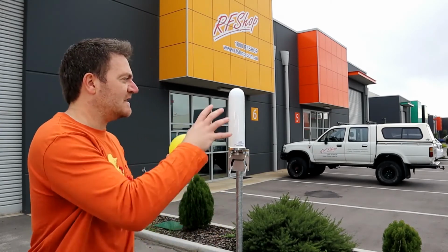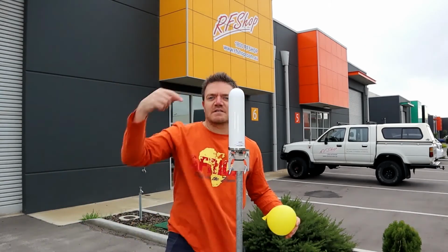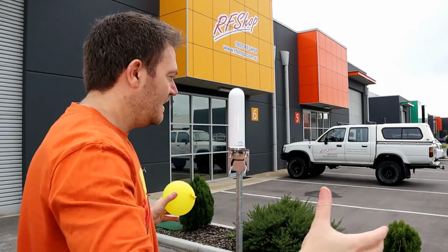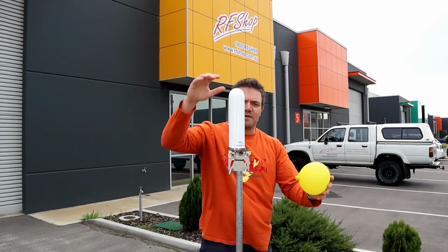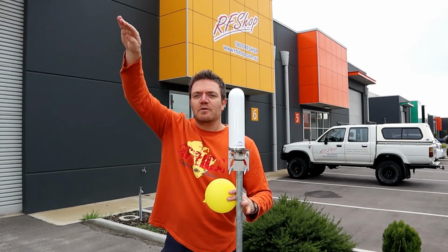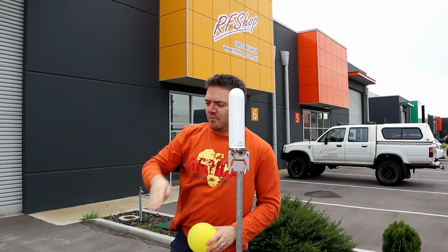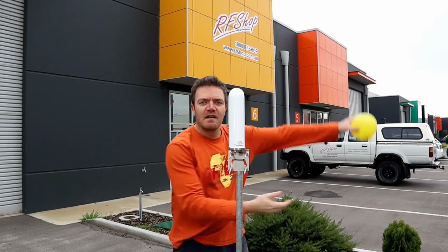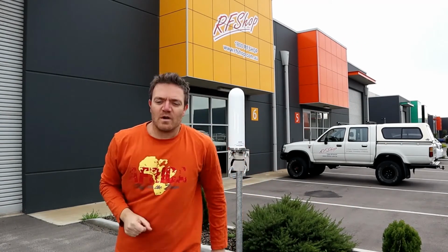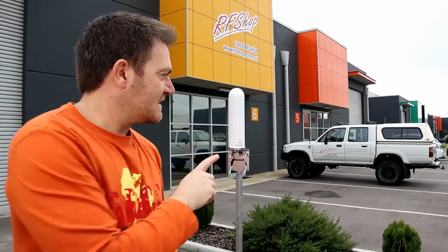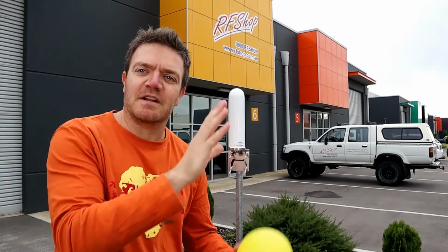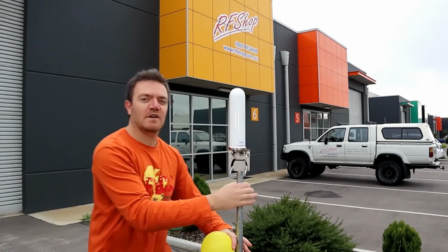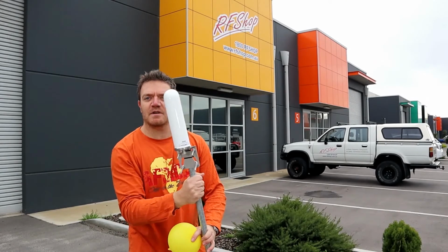And what the difference is, this one, it radiates all around. So wherever I stand around this antenna, it gives you some coverage. It's quite broad as well, so you can have an elevation or top and a bottom view that's quite good. So basically you would have a radiation pattern like this on this side and on that side as well. What's important there is if you have this is a marine antenna, so if it's on a boat and the boat is rocking left and right and so forth, so basically it goes up and down a bit like that.